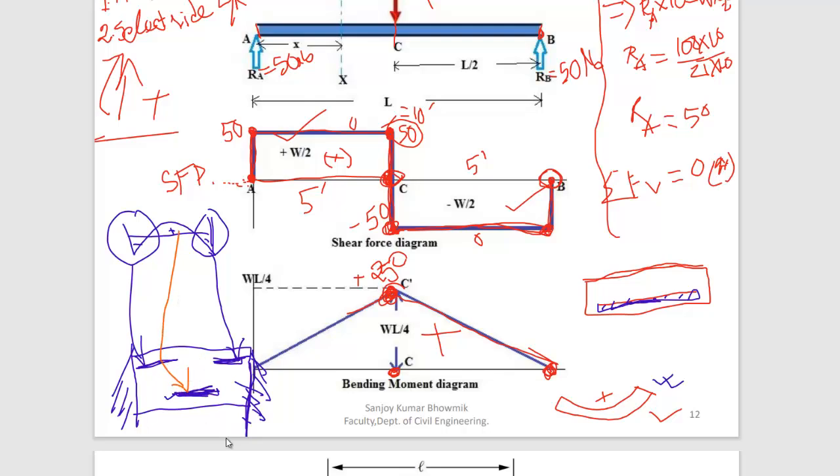Do you understand? So now if you look into the beam reinforcement detailing, you'll easily understand why they put more rods on the bottom layer in the mid portion of the beam, and why they put more rods on the top layer at the end of the beam. Do you understand now? Yes, sir. Interesting, sir. Yes, if you understand. Otherwise, you will say, sir, time's up.